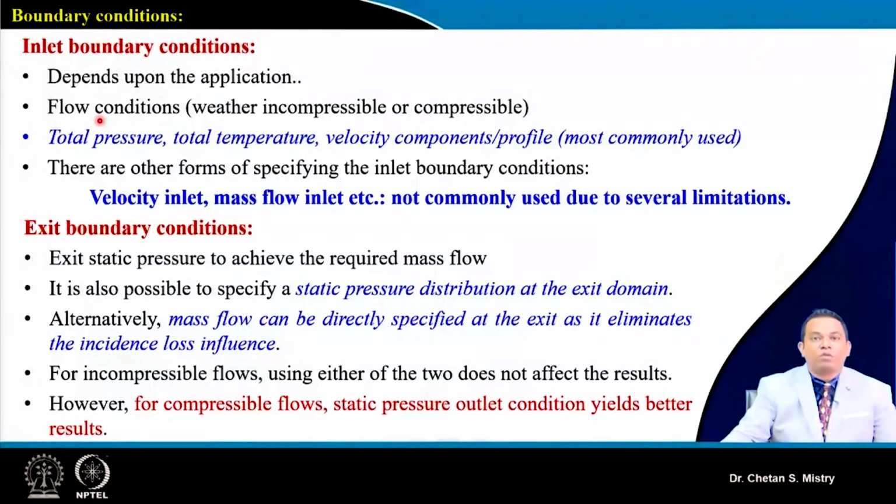You know better now. When we are considering a subsonic compressor versus a transonic compressor, that is what differentiates compressible flow and incompressible flow. So total pressure, total temperature, velocity component or profile is what is most widely used as an entry boundary condition or inlet boundary condition.